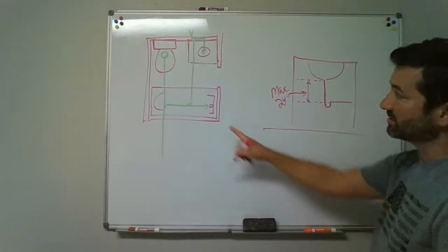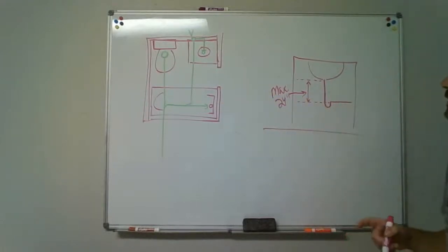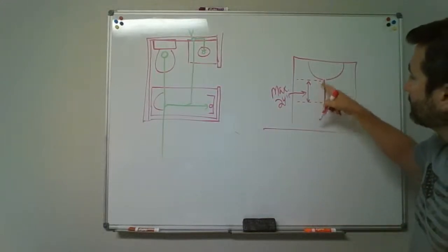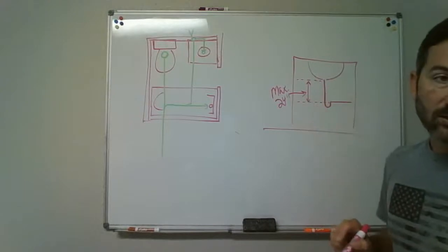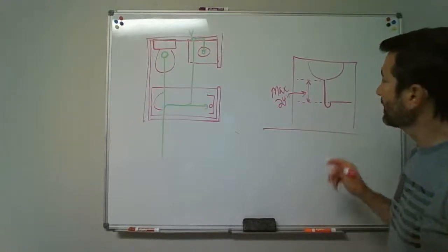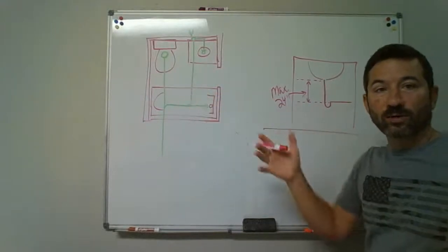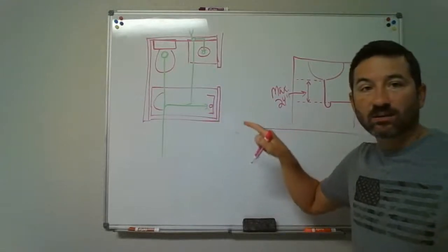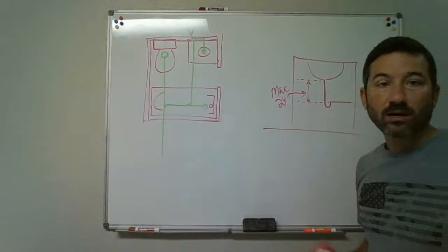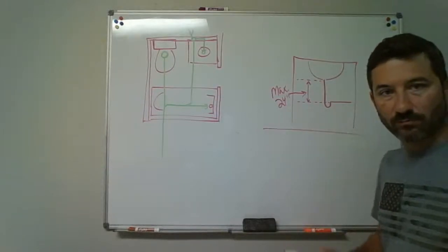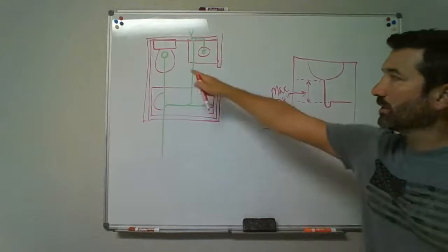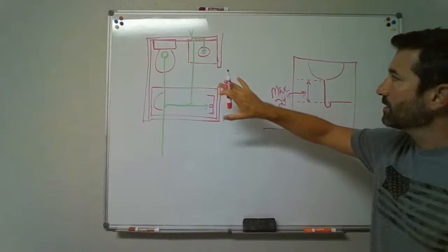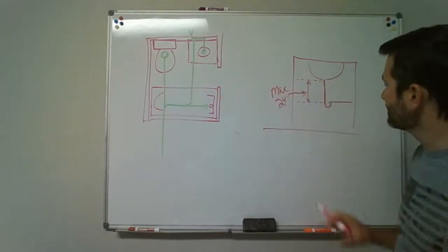Now, it doesn't matter whether it's the tub, a shower, kitchen sinks, whatever the fixture is, the maximum from the fixture outlet to the trap weir is not more than 24 inches. Now, we're trying to get all the drains below the floor so that we can hook them together up underneath the floor. The tub is easy when we hook that trap together. The trap is already under the floor, so we don't have to worry about how much drop. The toilet is mounted right to the floor, so that's going to go out the bottom and kick over. So we're not concerned about that exceeding this drop.